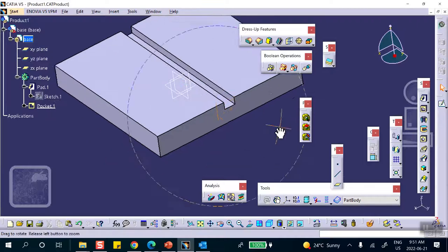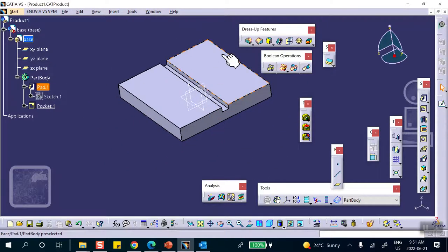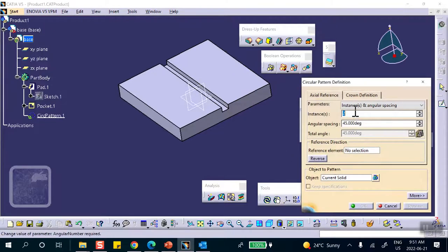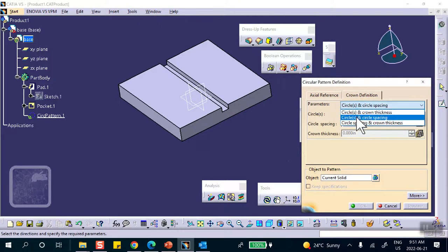And since I am kind of lazy here, instead of making another one in the other direction, let me use this thing called circular pattern. Okay, two of them make a complete crown. No, hang in there. Okay, crown is good. Two, and I don't want the whole solid.